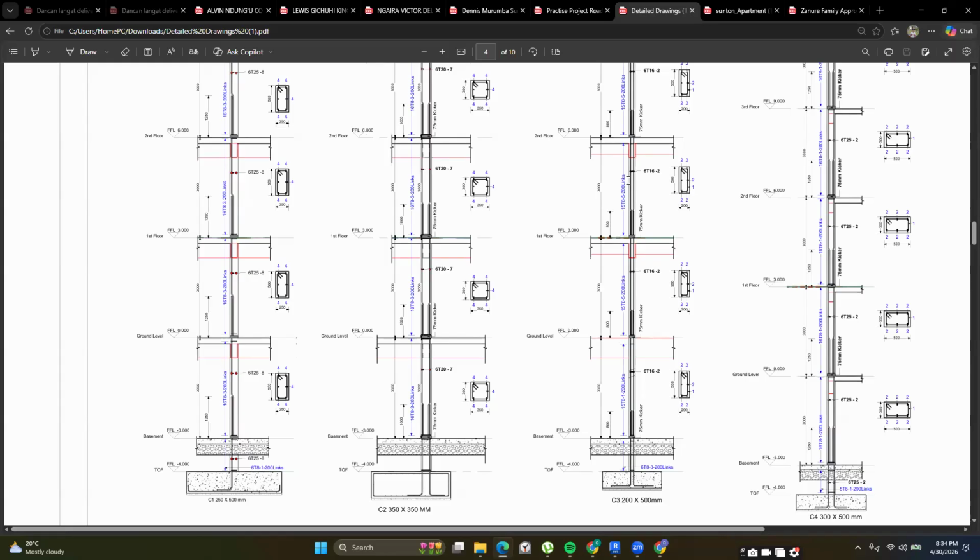But as you work with the software the second or the third time, you need to reduce the amount of effort you put into setting up the software. You do not need to create multi-rebar tags every time you use it. You do not need to annotate your beams manually every time you are working on it. So after you've worked with the software a few times, you can create a standardized template just to make you a bit faster and also to standardize your work. So that is what a template is. It is just a group of preset settings and loaded families that facilitate your workflows.